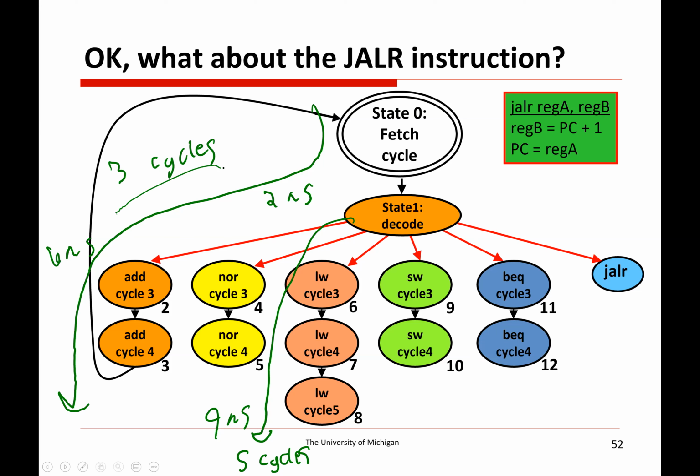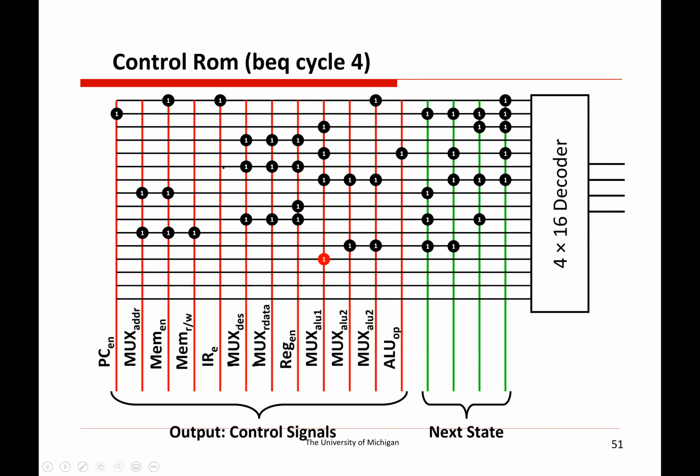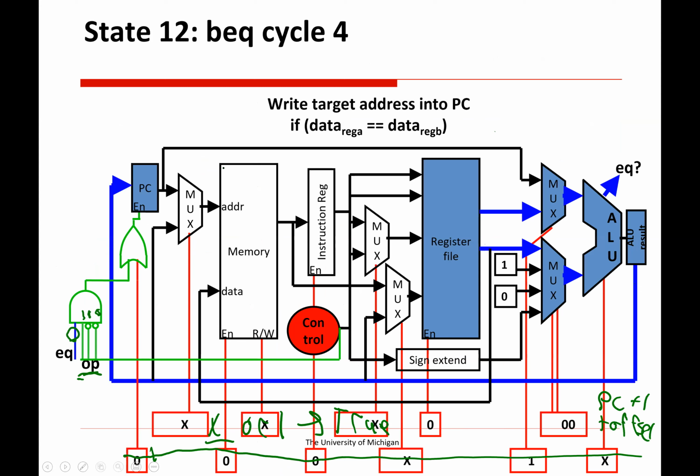So Norman asks about the left mux that goes into the register. This one here, is this what you're asking about, Norman? Okay, so yep, so this is the write register index. And the reason why we have a mux here is because there's 2 different types of instructions, add and nor. We have R1, R2, R3. This is the destination register for those, so that's what we want to feed in for the index.